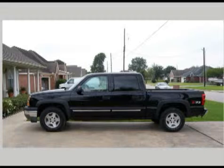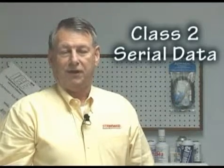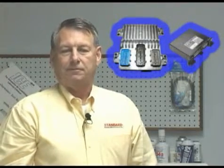The vehicle, which is a 2006 Chevrolet Silverado with the 5.3 liter engine with automatic temp control, has a possibility of up to 12 separate control modules on it. The HVAC system alone uses Class 2 serial data for communication, as well as high-speed CAN serial data. For this reason, we will attach a scan tool as our first step in diagnosis and check for diagnostic trouble codes in both the powertrain control module and the body control module.